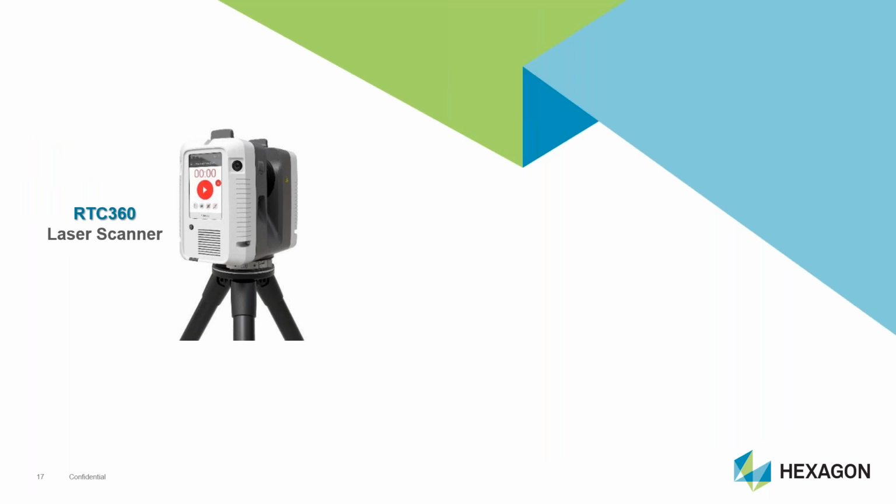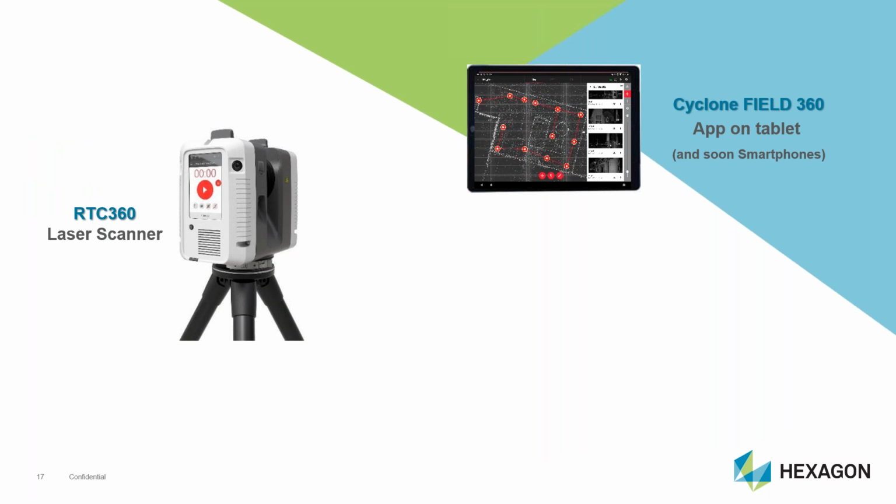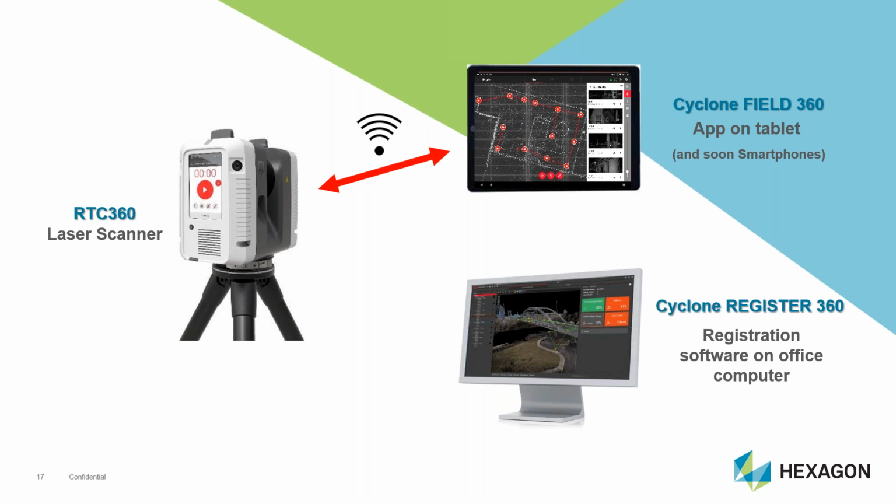So here's the scanner itself. Here is Cyclone Field 360, and soon smartphones, but we've just released the app for iOS and Android for smartphones. So that communicates wirelessly with the RTC 360 scanner. And then in the office, we have Cyclone Register 360. So there's a USB storage device in the RTC 360. We just drag and drop the data into Register 360 and start processing that data into our final colorized point cloud, our panoramic imagery, ready for use downstream.